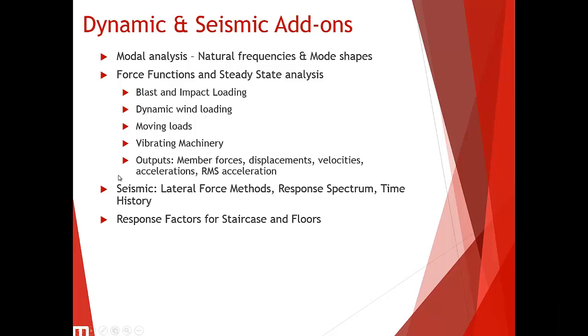Or we also have the seismic add-on, and this includes some lateral force method calculations, the response spectrum method, and a full time history analysis with base accelerations. And finally, we have the response factor tool, which is becoming very popular, and this can be used to limit the sort of vibration response of your staircases and floors.